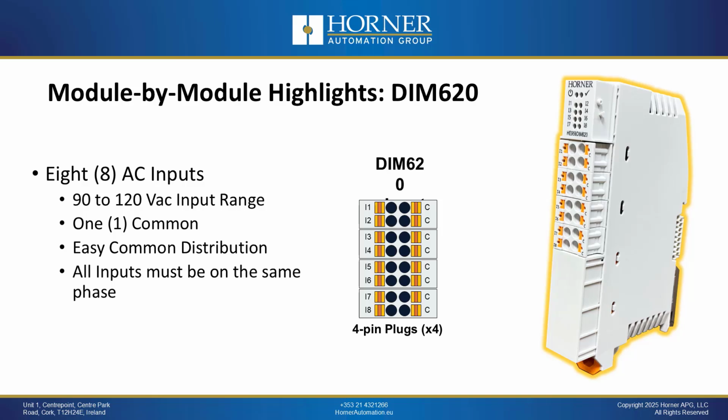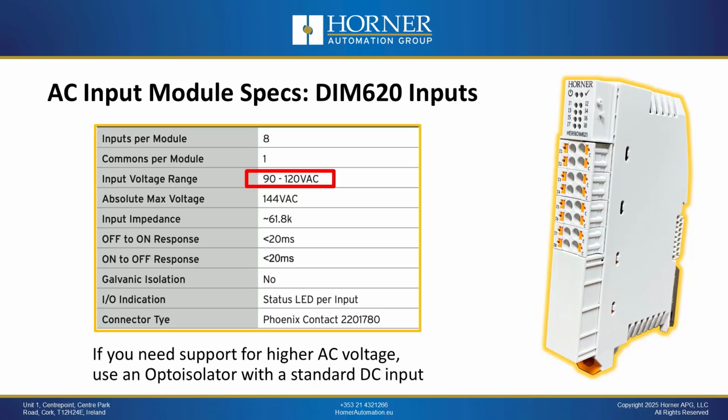It supports voltage up to 120 volts. If you have voltage higher than that, you will need to use an opto-isolator. But you have got your 8 inputs, and a place to connect your L2 or common type connection here. It is really easy to integrate. Once again, it is limited to 120 volts AC, so keep that in mind, but that is a majority of what the applications are anyway.